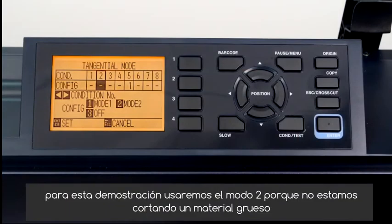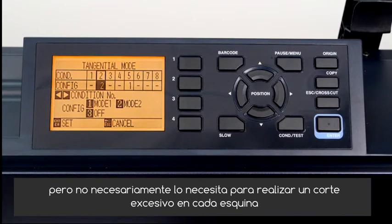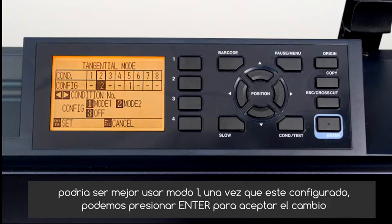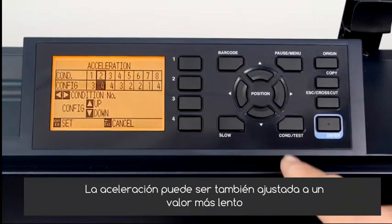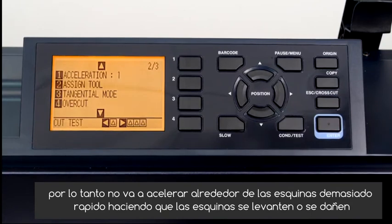For this demonstration, we will use Mode 2 because we are not cutting a thicker media. So we want it to lift up the blade to maneuver it at the corners, but don't necessarily need it to perform an overcut on each corner. As a note, when cutting intricate graphics on media that is perhaps more pliable, it may be best to use Mode 1. Once that is set, we can press Enter to accept the change. The acceleration should also be adjusted to a slower value so that it won't accelerate around the corners too fast, causing the corners to lift or be damaged.